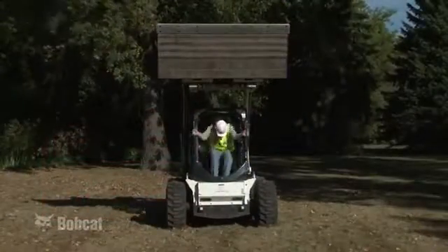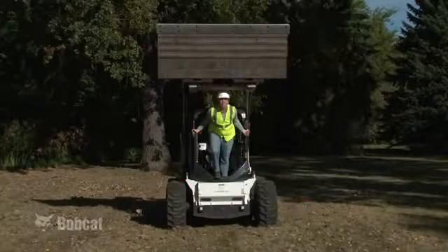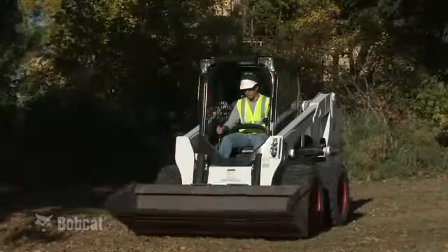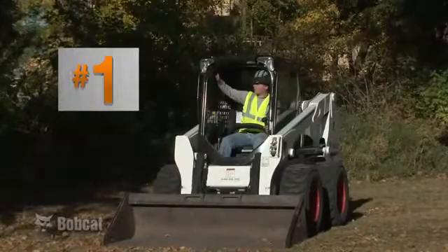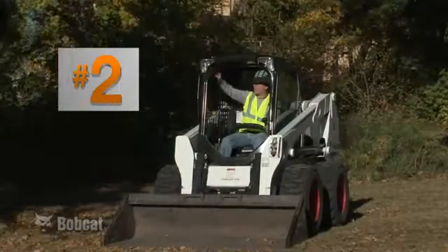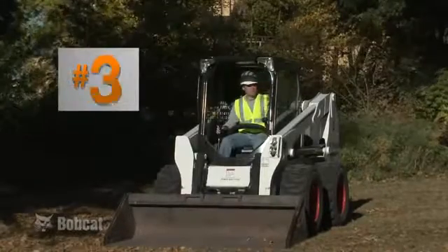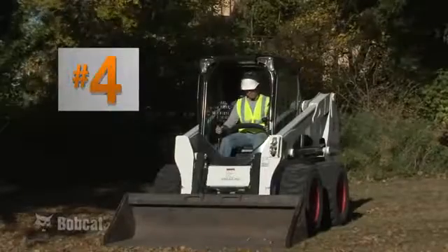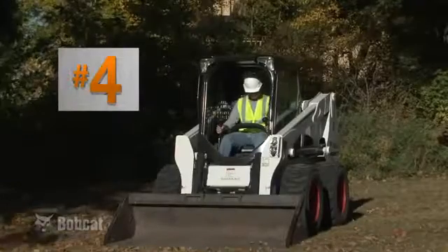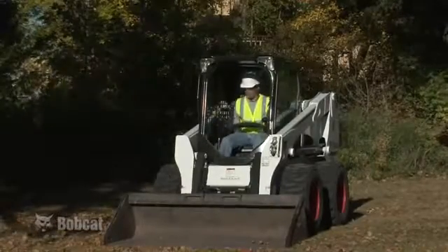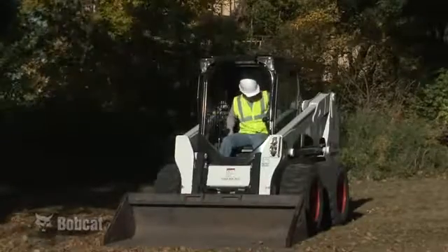When parking or leaving the loader, never leave the loader seat with lift arms raised or with the engine running. Remember, always lower the lift arms and attachment flat on the ground. Stop the engine. Remove the ignition key or lock the keyless panel to secure the machine. Engage the parking brake. Move the controls until they're locked or in the neutral position. Follow the procedure outlined in the Operation and Maintenance Manual and on the loader's machine safety sign or decal.